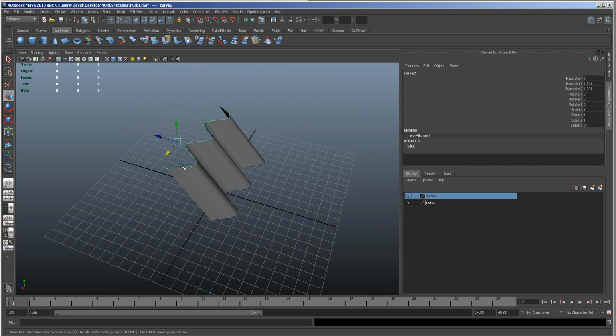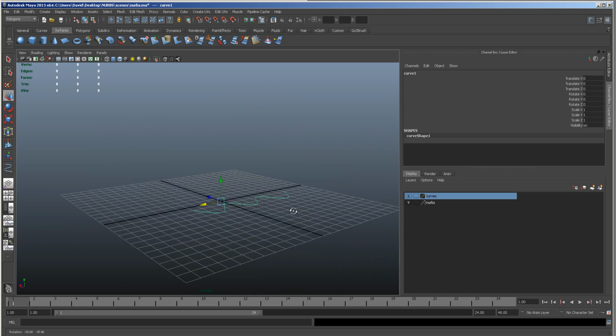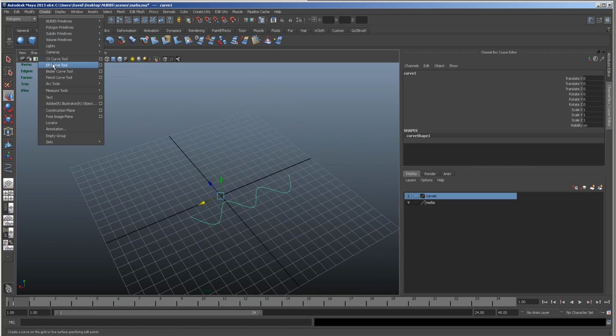Now there are things to consider. At the moment we've just been duplicating a face, which is all very well and good, but there'll be times where you want this curve to run into another curve that's different, especially over something like a car. So let's do that. Let's create another curve and pretend we're putting it in position.